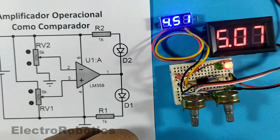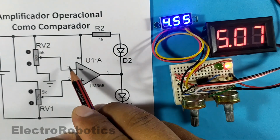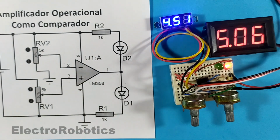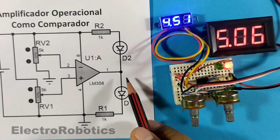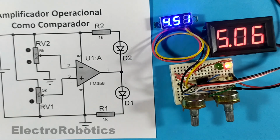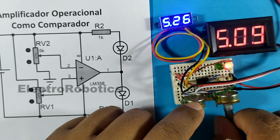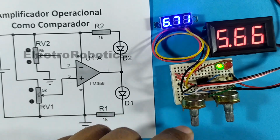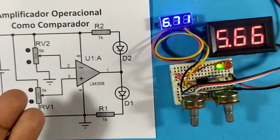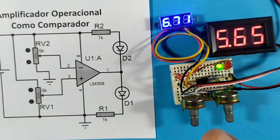You see, a comparator works like this, comparing the voltages of its pins, both 2 and 3, and depending on the result at the output, we will have negative or positive, which will make one or the other LED turn on. There. And there. On this occasion, the operational amplifiers are working at 12 volts as indicated by the circuit. Well, now let's see how it works as a signal amplifier.